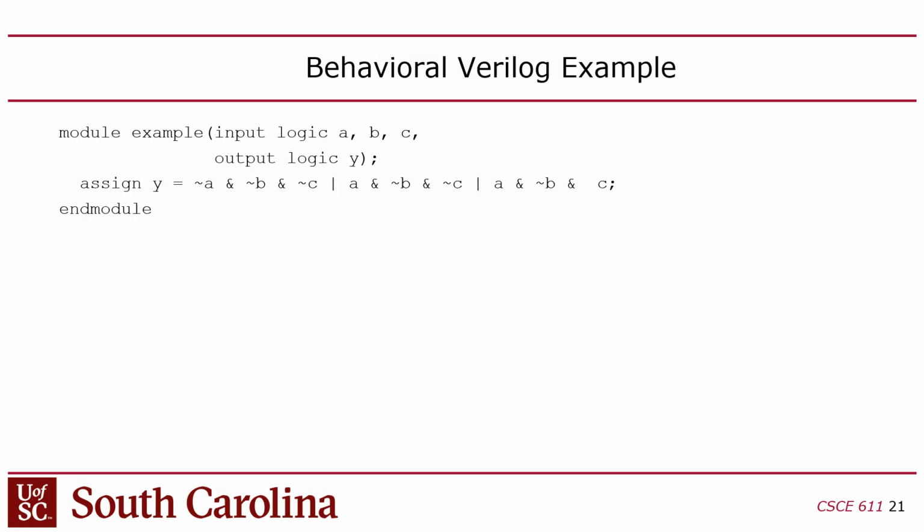So now there is a type called bit, and bit is actually just a 0 or 1. But I don't know, and this is just my naivety, why anyone would use a bit, because it makes more sense to use a logic, because it aids you in debugging: you can detect floating and double-driven signals and such. Okay. Oh, by the way, there is a compiler you might have heard of called Verilator.